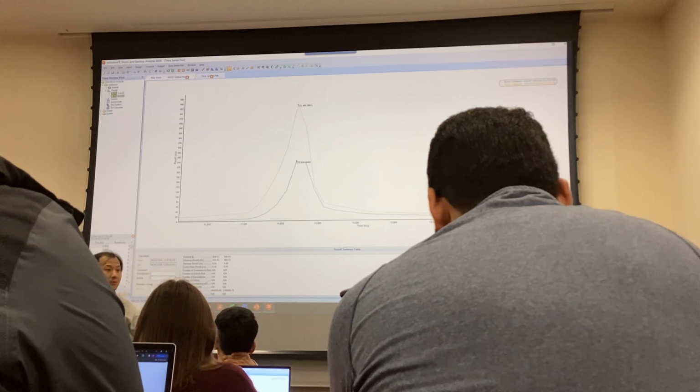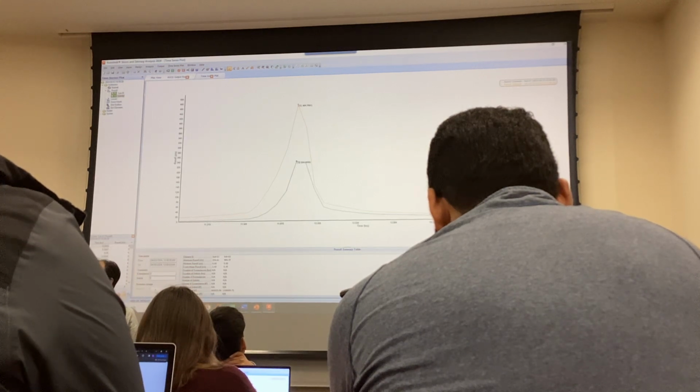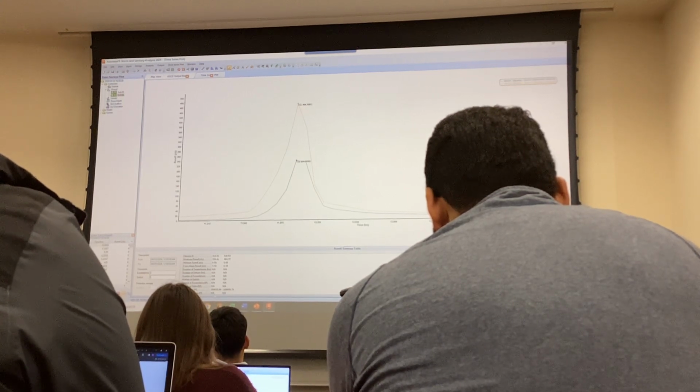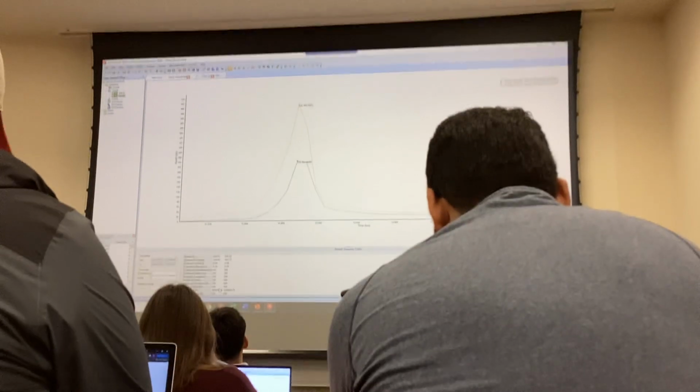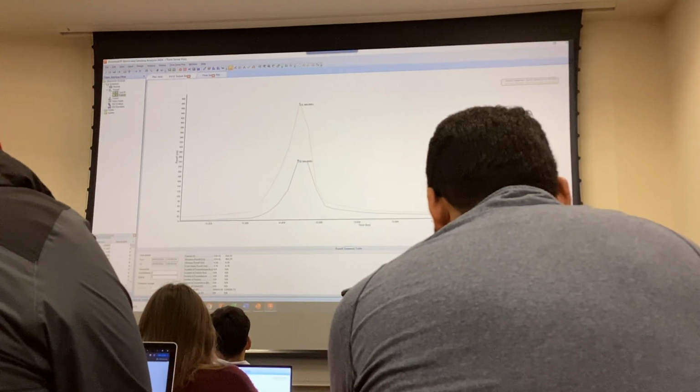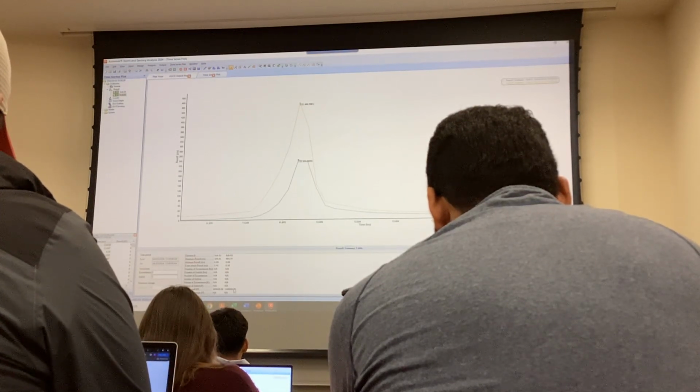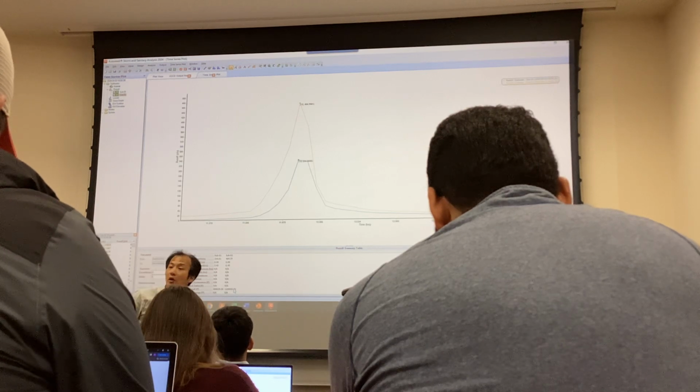And in this case, our maximum flow is going to be the pre-development flow because we don't want to exceed that, right? That's the maximum that we have described. So you can put it in there, and once you put it in there, it automatically spits out the volume that you need somewhere over here. Yeah, detention storage. It automatically spits out that value once you put in your maximum outflow.